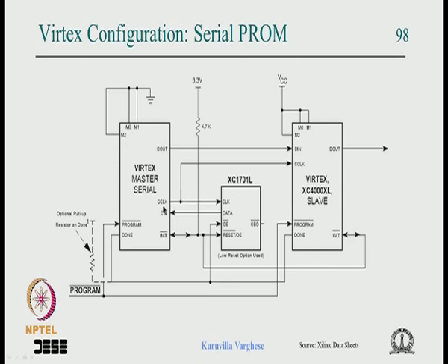At the beginning, at power on, the FPGAs start programming, or if there is a program pin and the program pin is made low, if you apply a negative pulse, then it starts programming anytime.